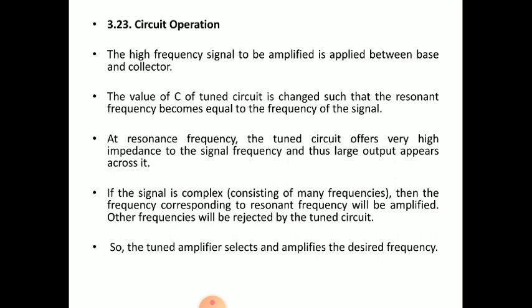By turning a particular knob on the device, we are actually tuning to the incoming signals. That is, we are changing the C and L values and tuning to the desired frequency. Whenever the frequency matches the incoming signal, the maximum gain will occur and the output will be an amplified version of the desired signal.